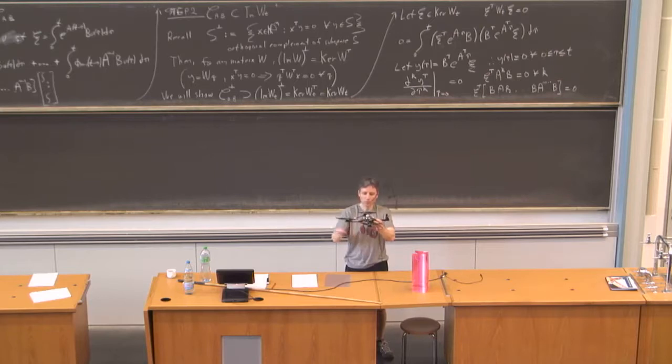If I want this thing to roll, I speed this down, and I speed this up and I slow this down. The net thrust going up is the same, but it will create a moment that will want to make this thing roll. If I want to have this thing pitch, I do the same thing here. I speed this up, I slow this down. The net thrust remains the same. These guys are still producing the same amount of thrust, so the only torque is produced in this direction.